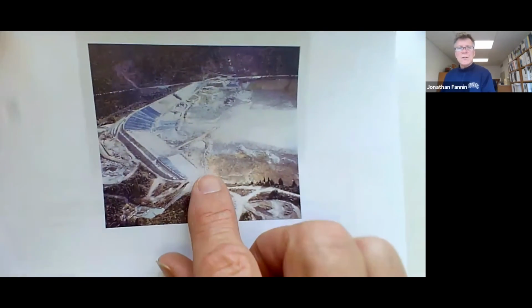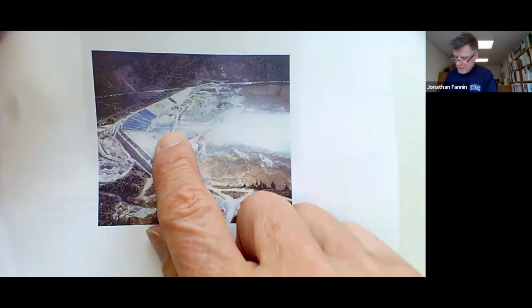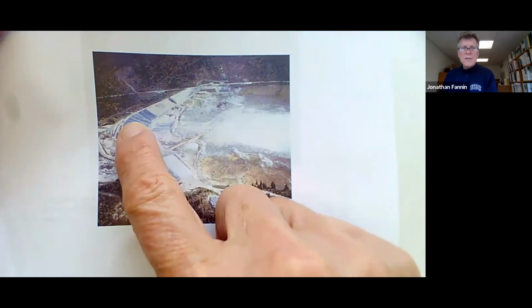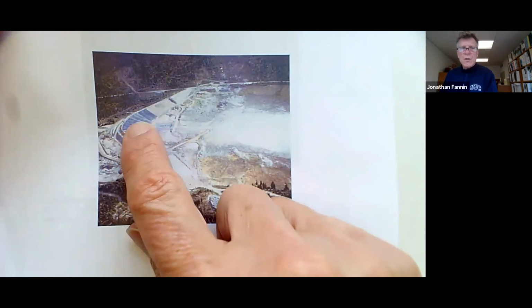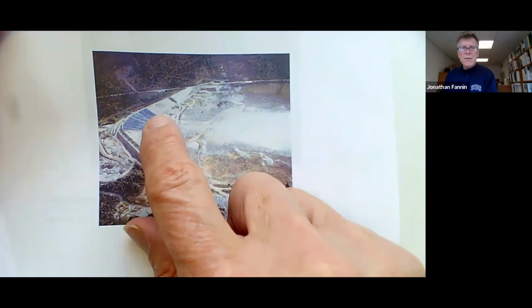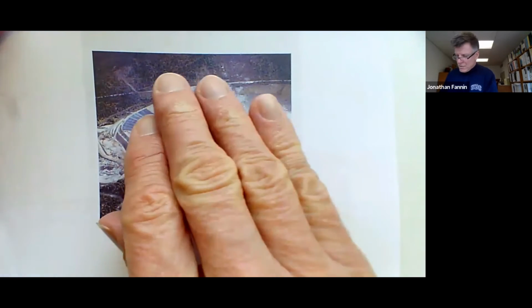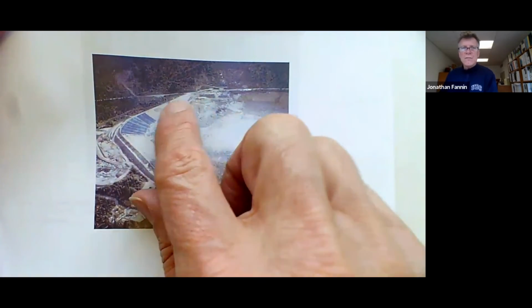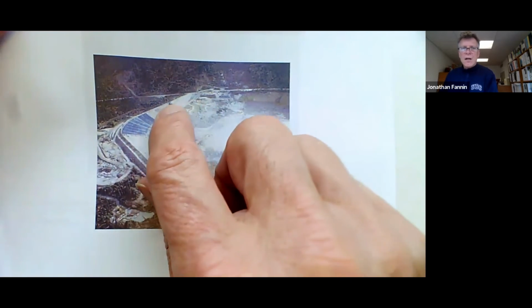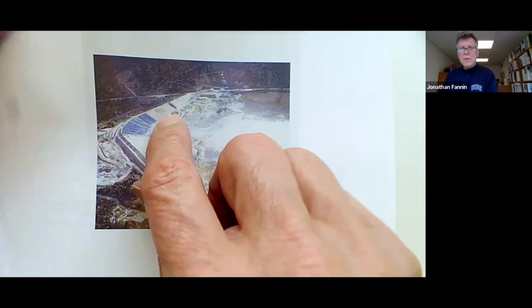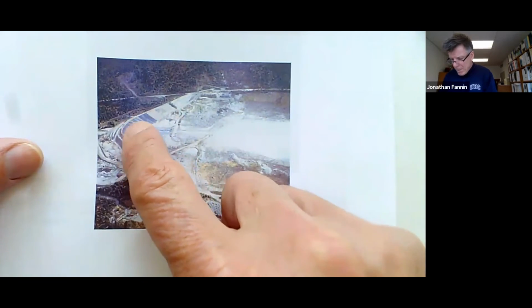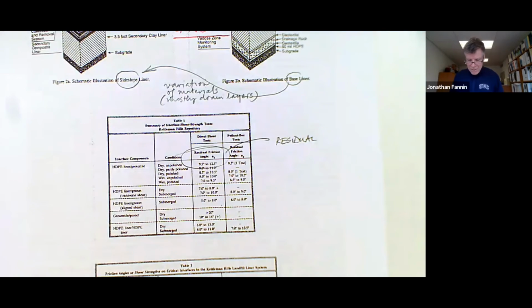Here's an image that I took coming into the site, and here's the geomembrane. There were two patches, one patch here and one patch here. The reservoir has been drawn down to facilitate access, cover material stripped off to expose the core of the dam, and the membrane panels are being placed.